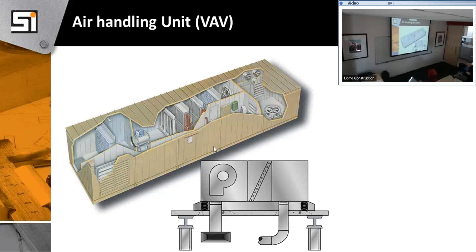In the older days, I would have to count the seats and always dump all this fresh air in here. So now code is requiring CO2 sensing. The sad part is I would always have to plan for a lot of people, so let's say I put 500 CFM of fresh air in here. But when it's just two of these guys talking in here by themselves, I'm wasting all this energy, taking this 500 CFM and reheating it because I don't need it.